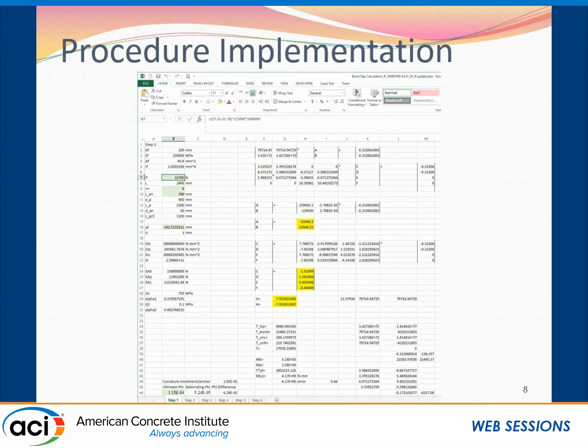I should note that one of the parameters used is the location of the last anchor. So at first debonding at the last anchor, we utilize the maximum spacing between the anchors. And if we converge, we say that debonding occurred at that anchor. And now in the next step, when we add more load, we'll actually change this parameter, which is LAN, right here. And the parameter now goes down to the distance between the plate and the next intact anchor. So we keep repeating this process for each anchor until we reach the ultimate load.